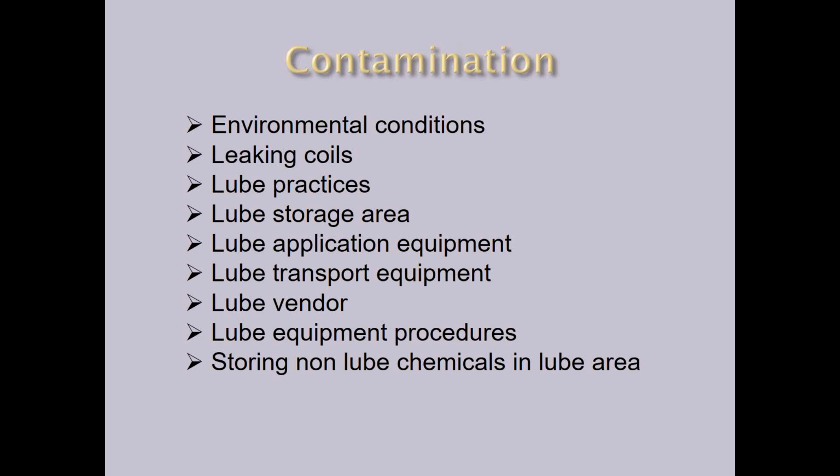Is there something getting in our lube that's not supposed to be? Is someone using a container that had antifreeze in it, and they're just wiping it out and then using it for oil or vice versa? That's going to cause contamination. It's going to cause your equipment to fail a lot earlier when those things happen. Again, all things that involve training.